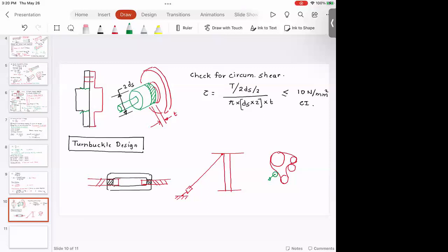Everyone understood this? So this tensioner also will have a turnbuckle. Some new vehicles, rather than a manual turnbuckle type tensioner, will have a hydraulic tensioner, which means instead of manually turning a turnbuckle, it would just have a hydraulic piston, and then you add the lever arm and pull this down and get that belt out. But if you look at the older cars, you would have a manual tensioner where you adjust the turnbuckle and that actually changes the tension or the load on the serpentine belt.